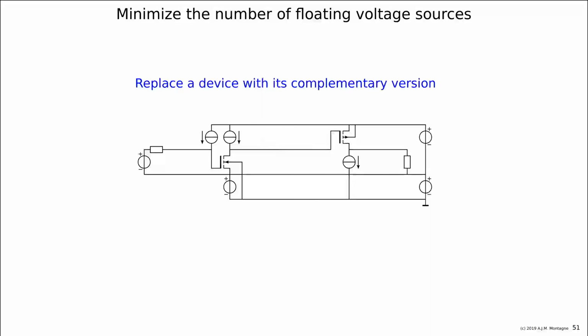And that's what I also did in the next picture, basically. You see it completely gone now. And for this reason, you could say I adjusted maybe VDS of the device so that I don't need this. If you do so, you just draw in your schematic the expected voltage levels there. So you start with the power supply and the gate voltage at the P device that is now connected with the source to the plus, some VGS lower than the power supply, and that sets also the drain voltage of the first transistor. So this is one method.